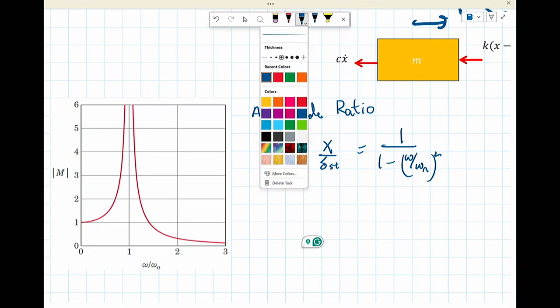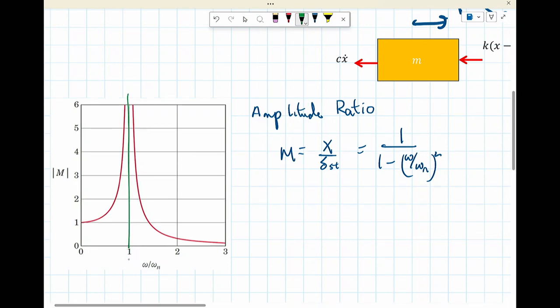But the relevance to this is that life, first of all, makes sure that every one of your resonance frequencies are in your engineering regime, and your life becomes misery, and you have to figure out ways to damp it. And say, for example, the Taiwanese earthquake, the other thing that might be interesting is looking at how they do the damping of buildings. For example, the largest building in Taiwan, I think it's World Trade 1 or something, actually has a damper that was tested in Guelph, Ontario. And it was part of their wind engineering work with RWDI.